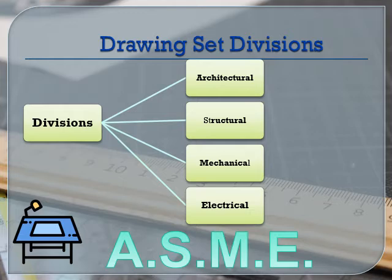And we talked about full construction sets and the divisions within those construction sets. So we had architectural, structural, mechanical, and electrical. HVAC is usually found under mechanical. If it's a really big project, they might have plumbing separately, but most of your HVAC information will be under mechanical. Of course, it's going to tie into the electrical, the architectural, and the structural, but specific HVAC info is in mechanical.